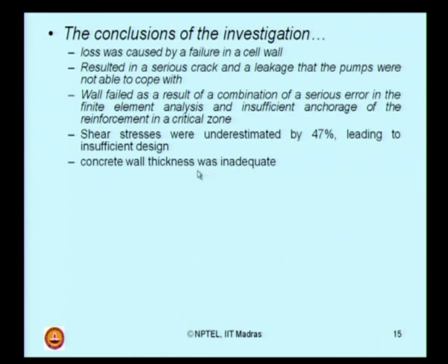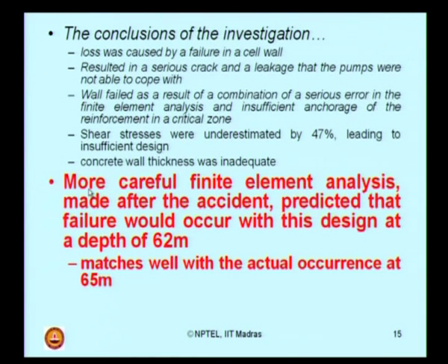You may wonder how such an inadequate design was deployed in a deep water platform. They were all investigations carried out after the accident occurred. That is what I am trying to insist here. So, a more careful finite element analysis could have avoided this, which was made subsequently after the accident, and that predicted the failure of this platform would have occurred with the current design at about 62 meter depth, and the actual accident occurred when it was at 65 meter depth.